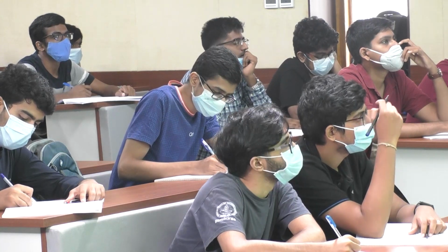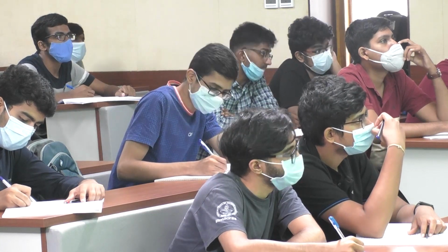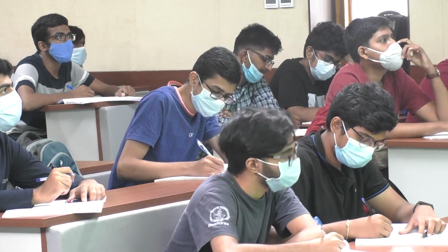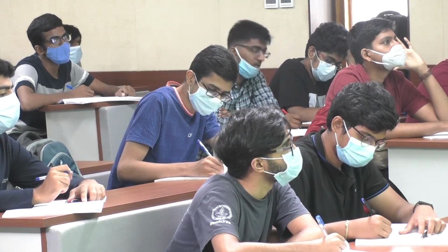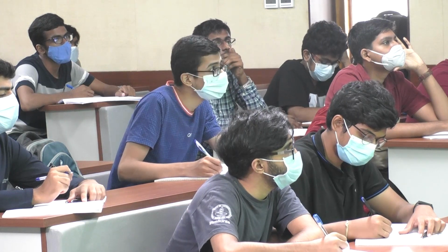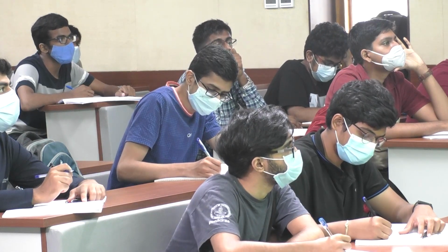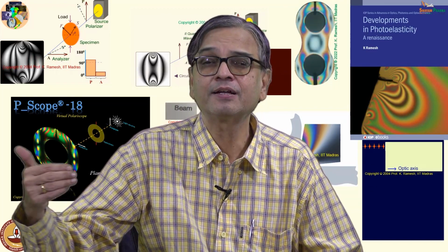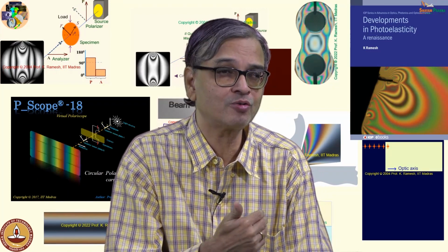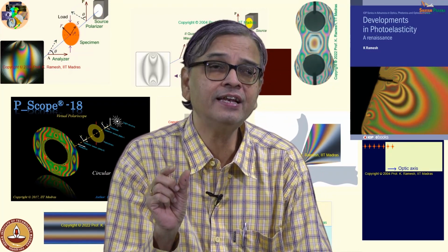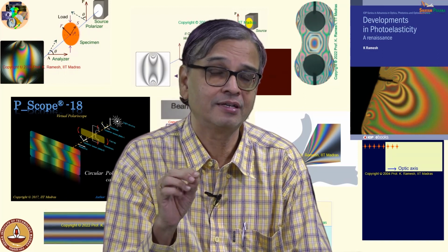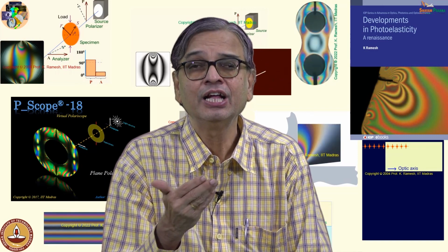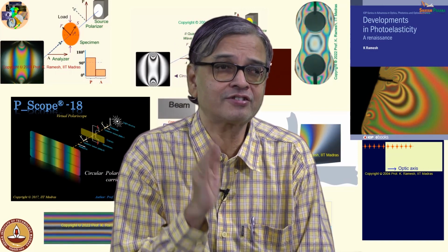Some of you, can you recall when we discussed uniaxial stress? I showed the model and then I showed the stress tensor. I said photoelasticity gives me only one quantity, and I said it plots sigma 1 minus sigma 2. Now you know the relationship. From a crystal optics perspective, when the light goes into a crystal and comes out, it acquires a retardation depending on the properties of the crystal. If I use a different crystal, it may have n1, n2 differently. Fine. And here we will relate it to the stress.